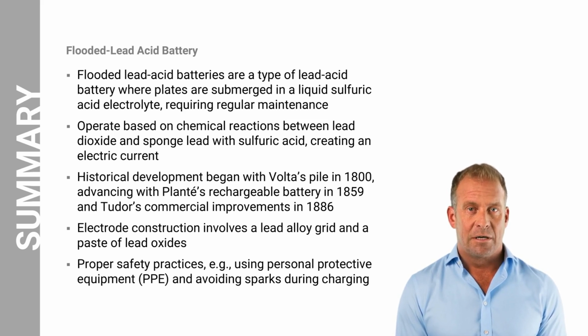Alloy compositions like lead antimony or lead calcium influence gassing and maintenance needs. Proper safety practices, such as using personal protective equipment and avoiding sparks during charging, are essential to prevent accidents and battery damage. Thank you.